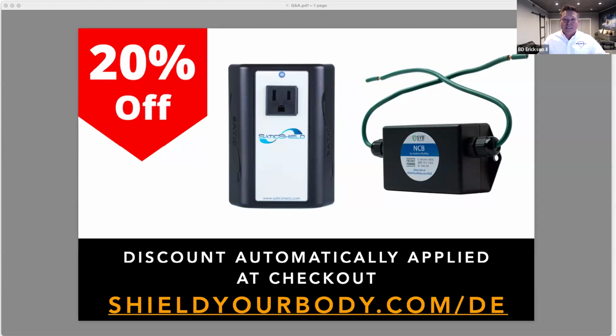It's there, you can see it. It's not real power. It's kind of like foam on a beer. Let's say half your glass of beer is beer and the other half is foam. Well, what's the foam? What's there? You can see it, but is it beer? It's not really beer. That's what apparent power is. It's there, it's apparent, but it's not real power. That's the difference between real and apparent power.